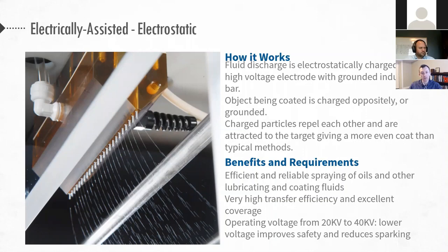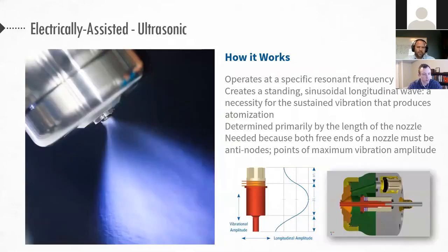But imagine if you had a surface below or something where you wanted all of the liquid to transfer directly onto the target. By charging the liquid, you can accomplish that. And if you've got a passing chain for lubrication, for example, then a solid stream is best because it's just going to all land. You don't have little droplets that you're trying to manage as well. It's all sort of staying connected, which is nice. This is different than electrostatically atomized sprays, which I think we'll maybe touch on the next slide, or one or two slides on.